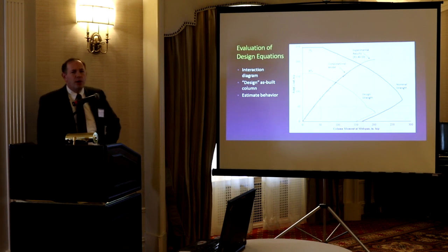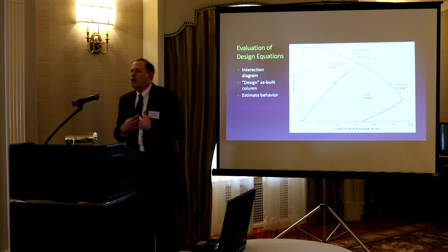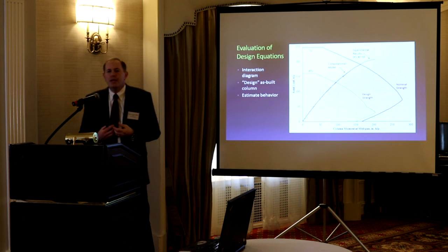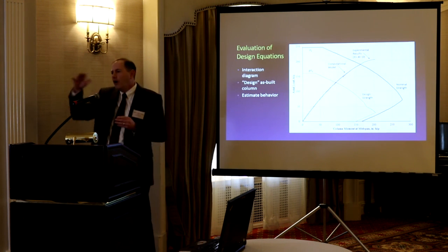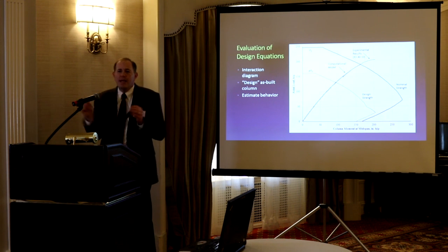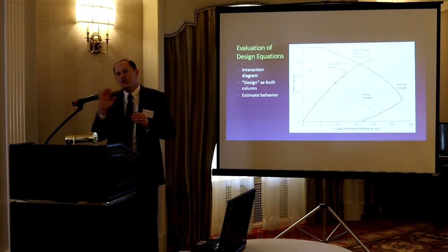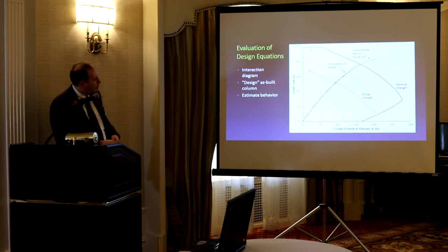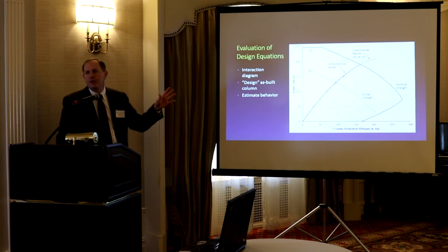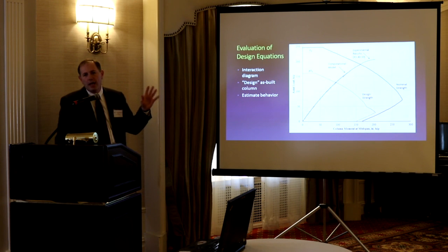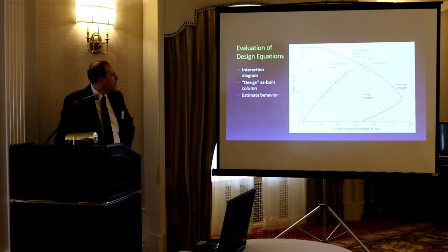There's our computational model. So when I say the model, again, there is no calibration of this model. This thing is just plugging in E of 57 root f'c. It's plugging in the Hognestad stress-strain curve. We didn't tweak anything to make it fit. It is just using regular mechanics, and we can predict the second order effects, short-term loads perfectly. I mean, it was uncanny how well these things can predict.